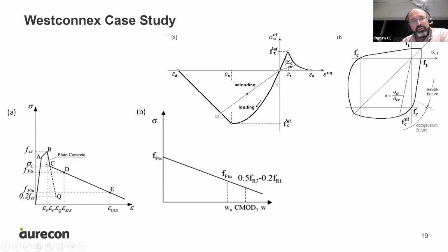And there are other benefits that we consider in our modeling too. When we have concrete, similar to soils or rock, if you have confinement, you gain strength. So we also include the benefit of what we call biaxial or triaxial enhancement in concrete. Once you have confinement, once you have restraint, that will generate those compressive membrane actions, or in-plane compression, that we discussed about. So we include that benefit, very similar to how it's done in soils and rocks, where you have friction and cohesion in a simple way. By the effect of having friction and confinement, you increase the capacity.